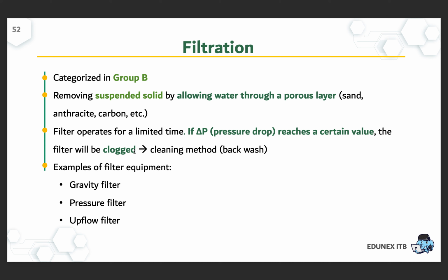In practical application, usually you will stop the filtration system when the filtrate is low enough. Every industry has a certain value, has a certain standard, or when the pressure drop becomes high enough to reach a certain value as well. So you don't need to wait until the filter is completely clogged.